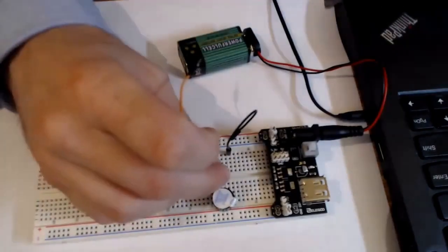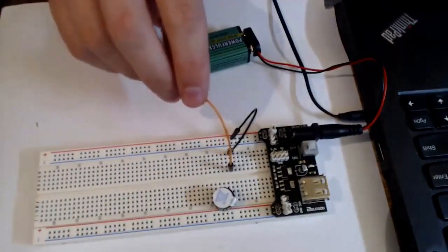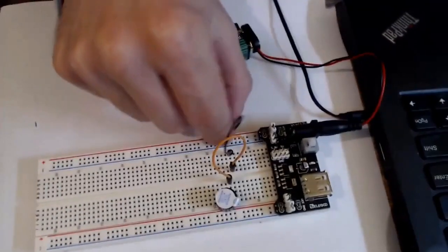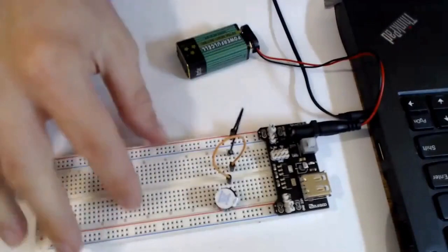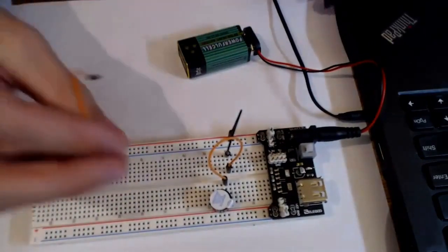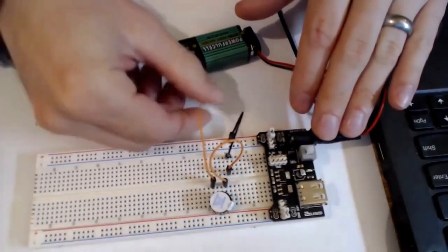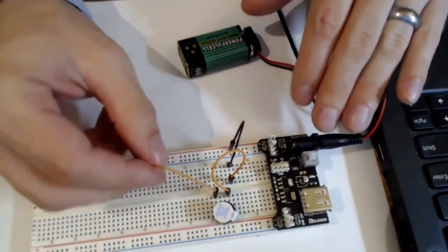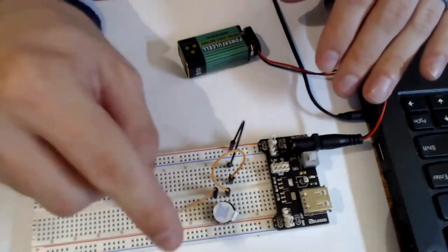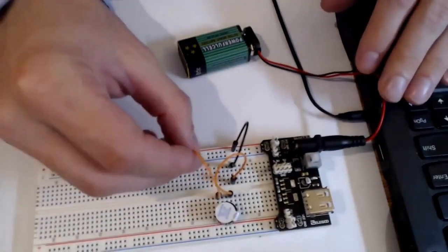So then we're going to cross that little bridge from E to F. Now the positive side of the battery has essentially contacted that one leg of the buzzer. And then from the other side of the buzzer, which is in column 23, we're going to do the exact same thing. Instead of just crossing the bridge and doing this separate stuff, I can now go from F23 all the way to ground, like that.